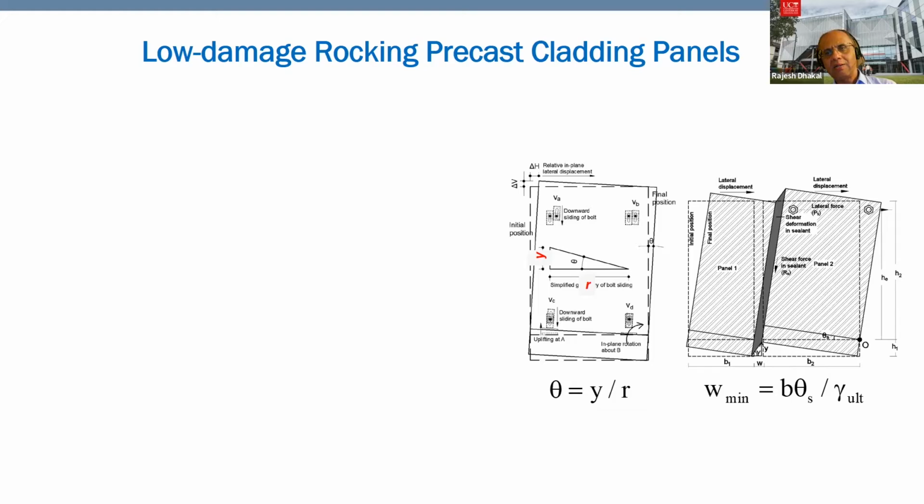Or the dimension of rocking arm length. Right? And similarly, between different panels, we have to use sealants to join them, and they are vulnerable to damage, but we can control their damage as well by just simply applying the basic mechanics. And if we know the sealant property on how much shear deformation it can take before it starts tearing off, we can control that by design.